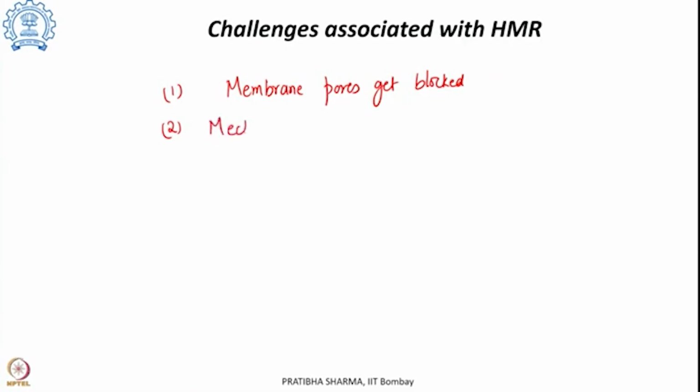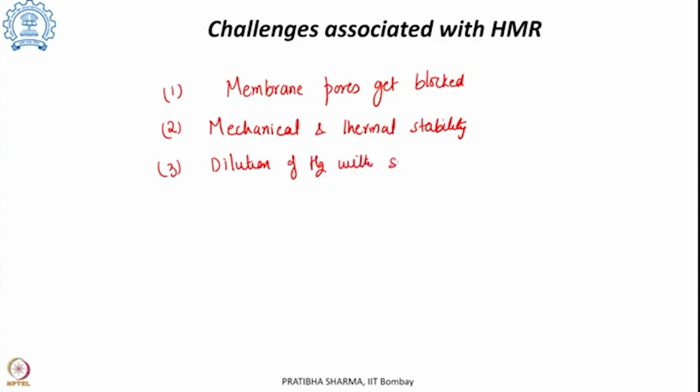There are challenges associated with the mechanical and thermal stability of the membranes. If we are using sweep gas, then dilution of hydrogen with sweep gas will occur, so again a purification to get pure hydrogen will be required.